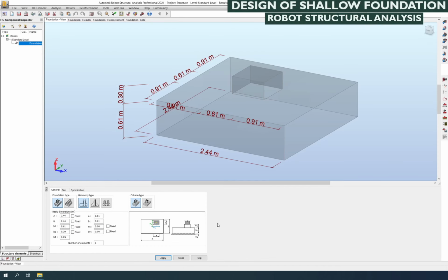In the bottom, you can see the dimensioning of a foundation, the input which is required for the foundation dimension to be provided here. In the middle, you can see the window showing the foundation dimension in a pictorial format. This is an uneditable format, where we cannot edit directly. Only through the dimensioning parameters in the bottom pane can we edit the foundation.